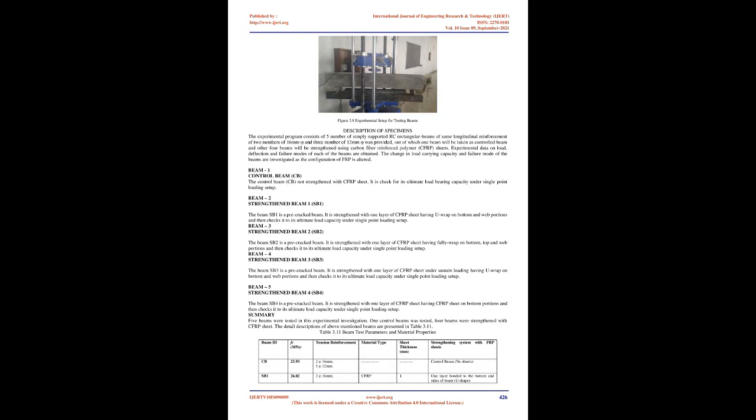Casting of the specimens. For conducting experiment, the proportions in the concrete mix are tabulated in Table 3.1 as per IS 456:2000. The water-cement ratio is fixed at 0.5. The mixing is done by hand mixing. The beams are cured for 28 days. For each beam 6 concrete cube specimens were made at the time of casting and were kept for curing, to determine the compressive strength of concrete at the age of 7 days and 28 days.